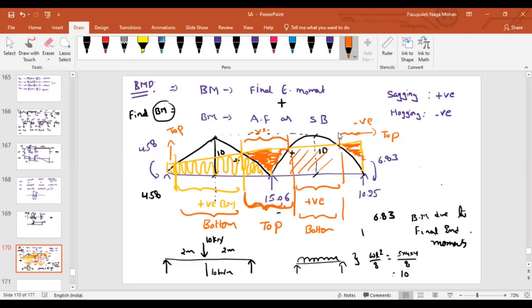So this is all general, common interview questions. They will ask you to draw the bending moment diagram, and based on the bending moment direction, you have to identify where the steel will be mounted. I don't know whether you guys have visited any construction site. If you have, you might see that wherever there are joints, additional reinforcements are provided at the top. Why? Because wherever there are joints, usually the tension occurs at the top fibers at the joint locations. That's why additional reinforcements are provided at the joints at the top. Clear? Any doubt in this diagram?